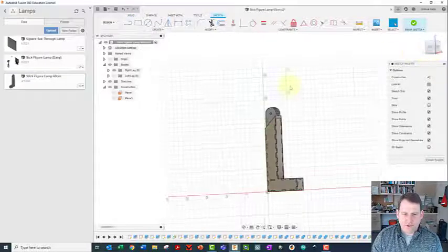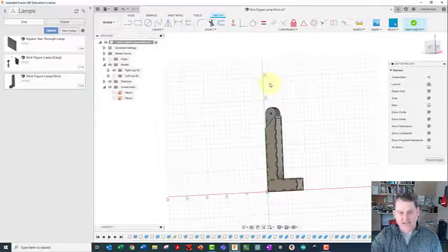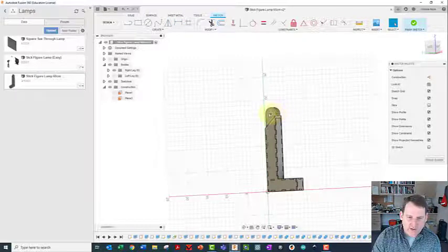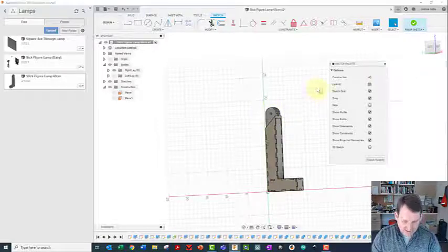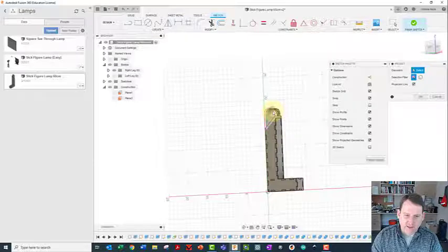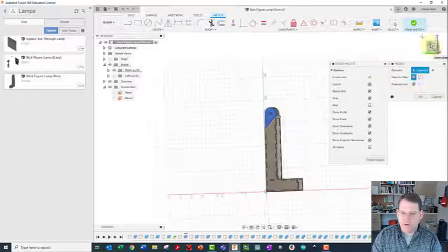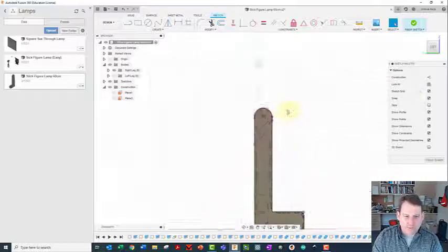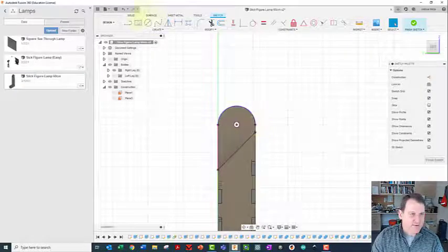So I'm going to extrude this thing to the inside. And what I want to do is project some stuff because I need to know where to line up my thigh. So the middle of the outside of the thigh should be right through here. Then the circle is going to kind of kick down below. So to be able to get this, I'm going to project this face onto my drawing. Click flat for my left drawing and click OK. This tells me where my rectangle needs to be.